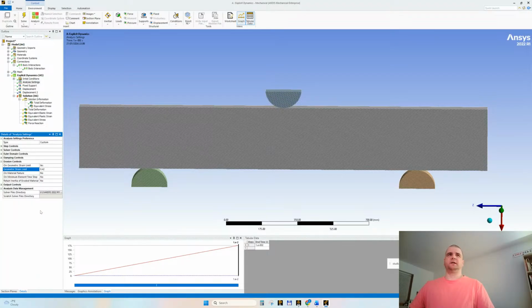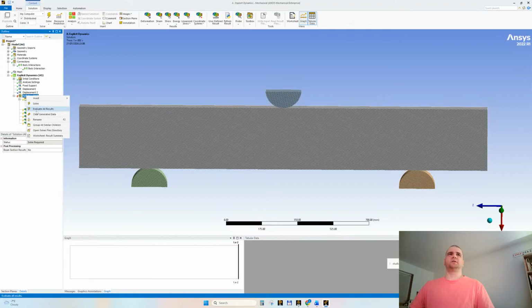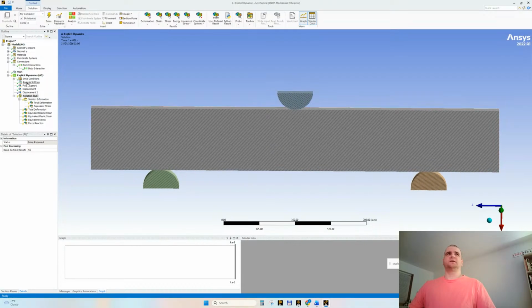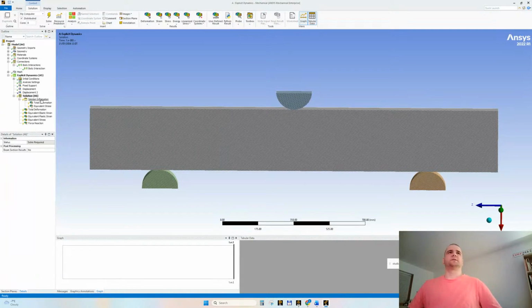And of course, each simulation engineer can correlate this value with the tests, with the visual conclusions, and we can edit that value for the geometrical strain limit. Let's solve like this. Now we will go towards a 15 to 20 minute solve. I hit save, let's hit solve again, and we will see the new behavior of the concrete.